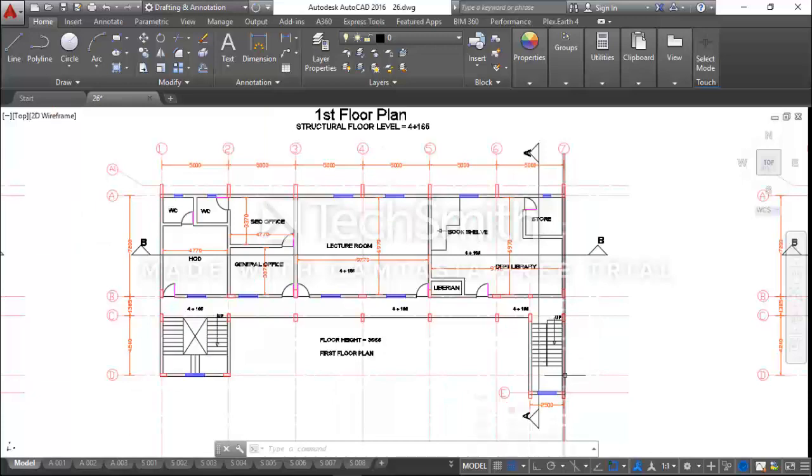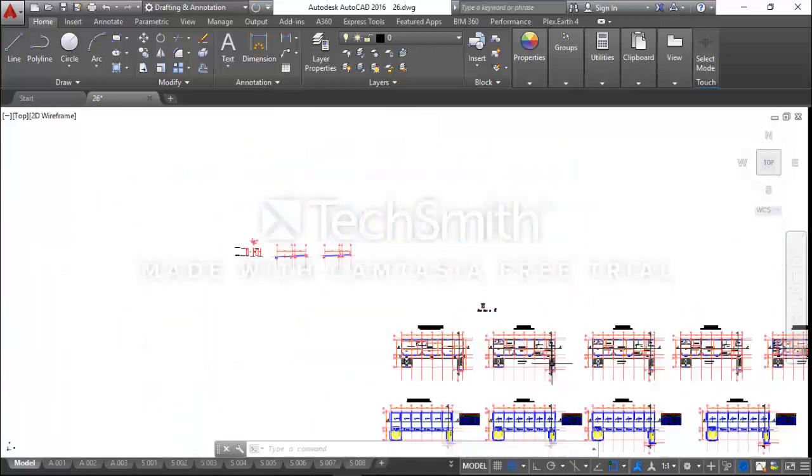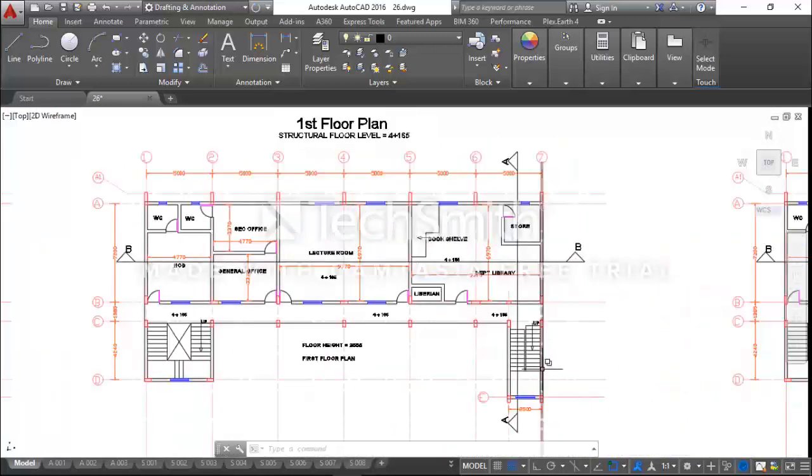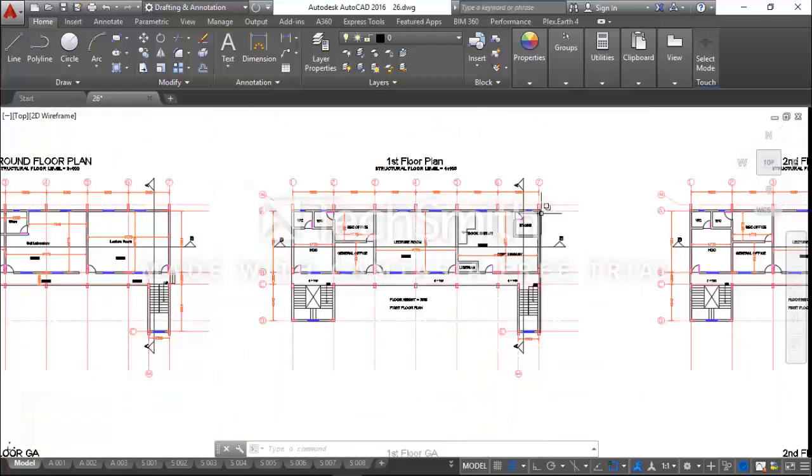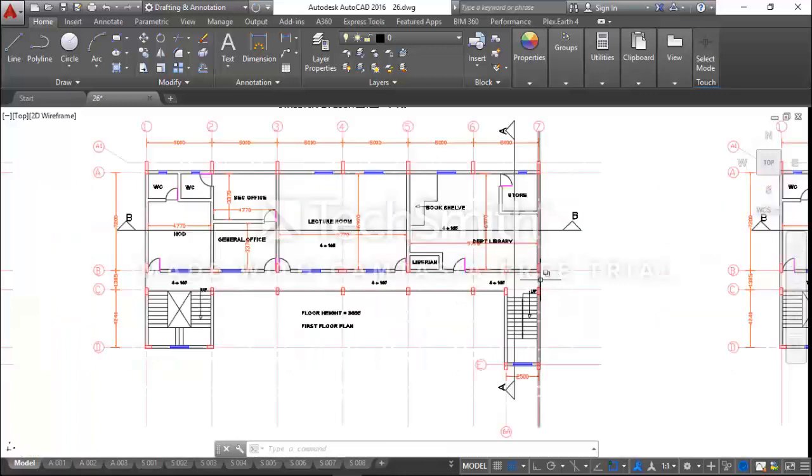This beam, if you remember, is located at the story level, so the wall height here will be 2.965. So I will specify my beam wall load along line 7, just that at the center between B and C, I'll provide a draft wall load of 1.5. So the wall height between A and B and between C and D is 2.965.